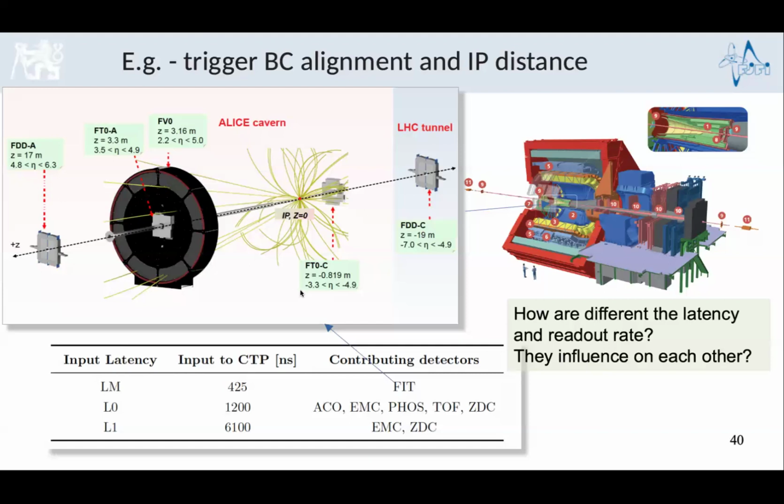And the cabling from this detector to the readout system is about 20-30 meters more or less. So if it's 5 nanoseconds times 30, it'll be like 150 nanoseconds more or less induced by only cables.